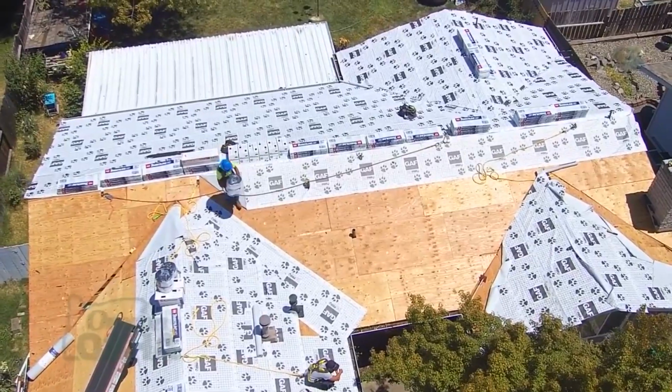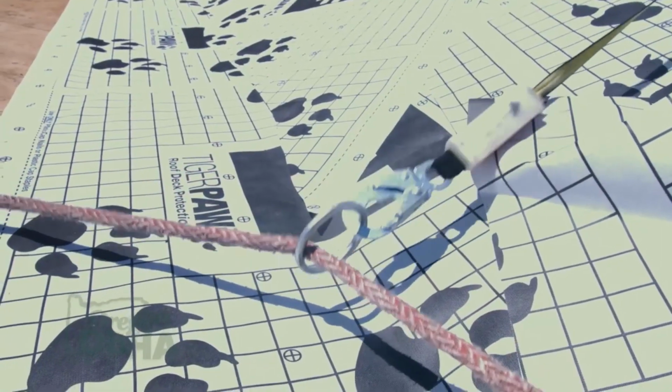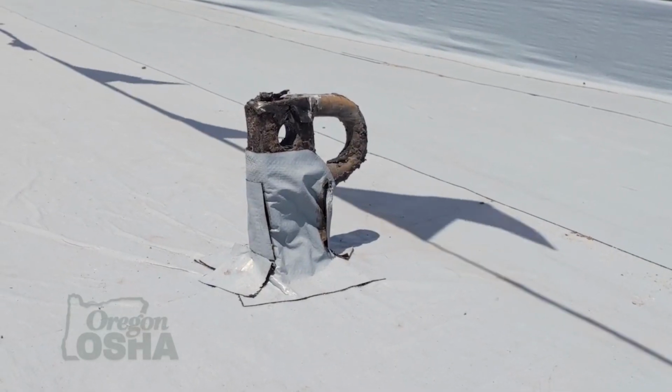On a situation where you've got a long ridge and it's two straight sides, you can hook up a horizontal lifeline, a rope that's got two different rings on it, and you can hook up a couple of different people on that lifeline and not have to have multiple anchors across the roof. That is really a nice system to work with if you don't have a lot of valleys or hips in the roof. If it's just two straight sides, that horizontal lifeline is a great option to go with. But again, you have to have the proper anchors to accommodate that system, which are different than your standard D-ring operations.